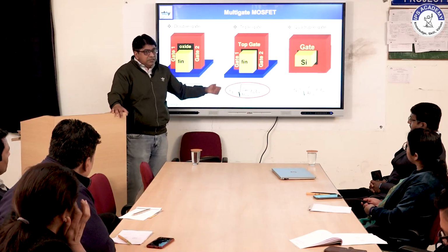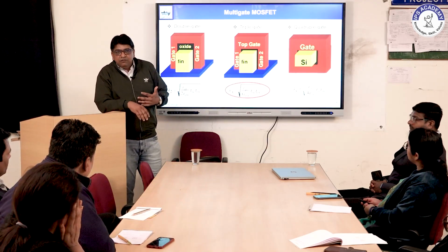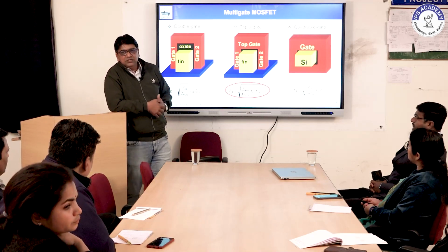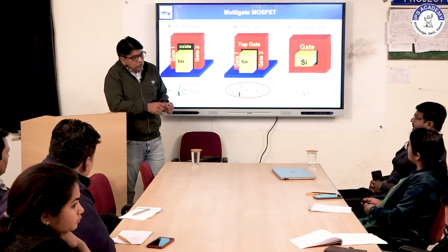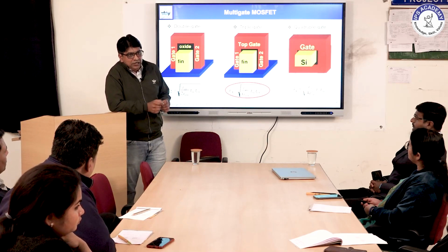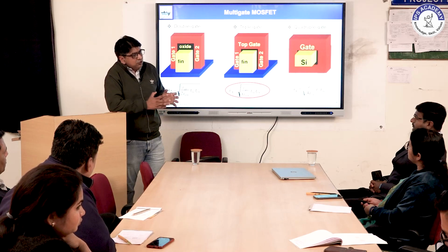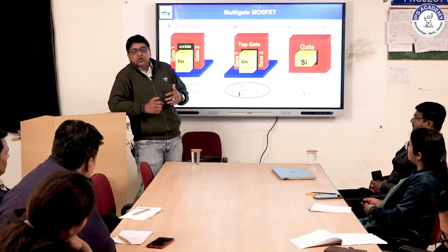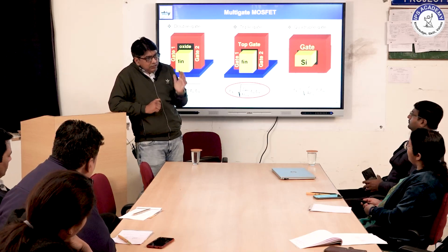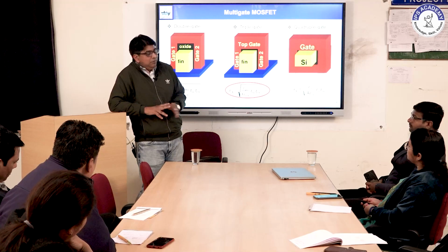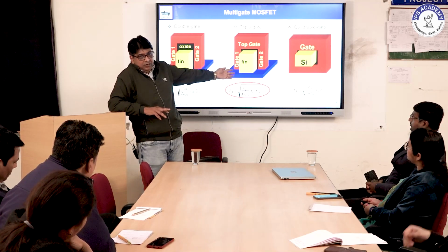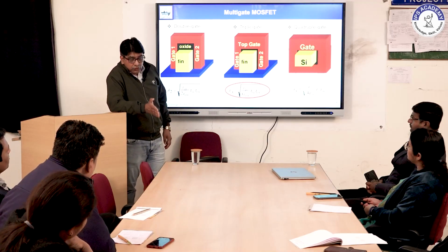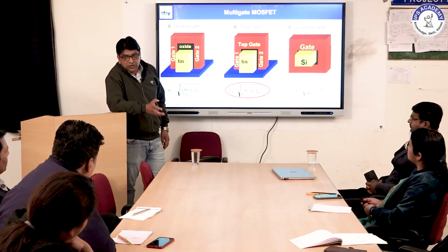Whenever we use a device for any application, for biosensing or for circuit applications, first we have to confirm that the device should not be leaky. If it is leaky, some short channel effect is there. You have to come up with some idea that will reduce such short channel effects. Like that, researchers introduced the tri-gate. This FinFET technology is heavily used, and it will continue up to 5 nanometers.